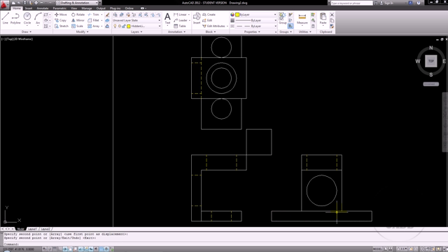And then the next thing I need to do is I need to locate those 3 holes over here. And the easiest way to do that is going to be to offset 20 with this line right here. I can now copy this, again, from that mid between 2 points, between here and here. I can copy that right to there.